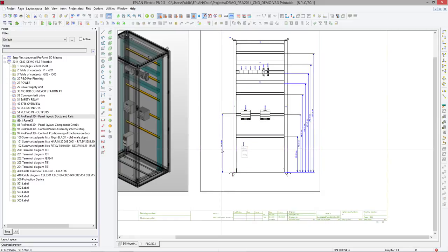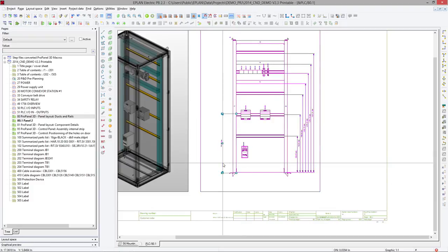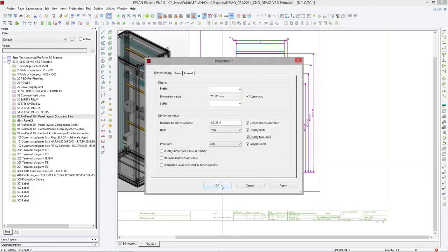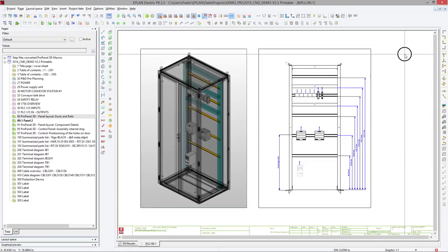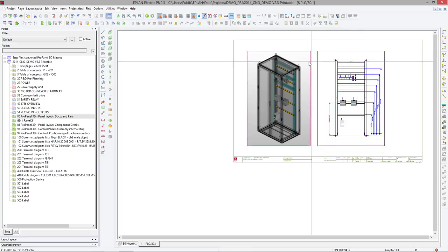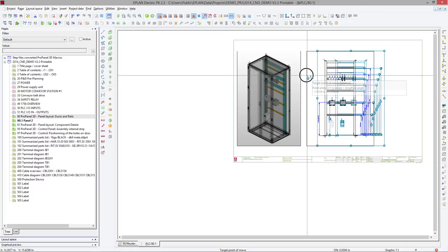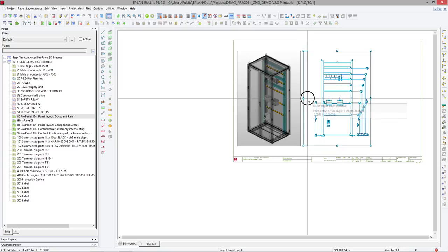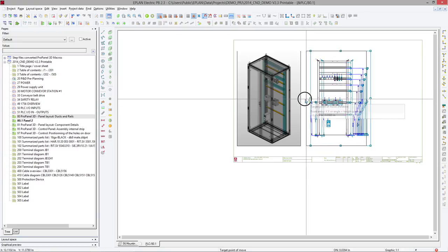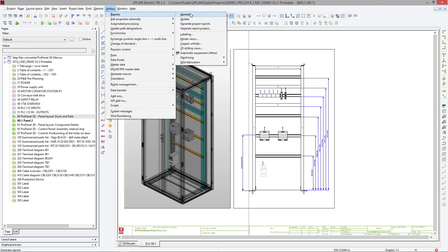Now, as you know, these dimensions can be modified slightly by specifying if you want 2 displays or 1 display, which means in inches as well as in millimeters. All the details are there. Plus, you can add on the top right-hand side here, if you have enough room. So if you want to make some room, you can move these model views a little bit to the side. As you can see, I can take these as blocks. You can even resize these blocks. If you can see that you don't need as wide, you can actually narrow down the block, and it's always going to be updated. And on the top right-hand side there, you can add an enclosure legend.